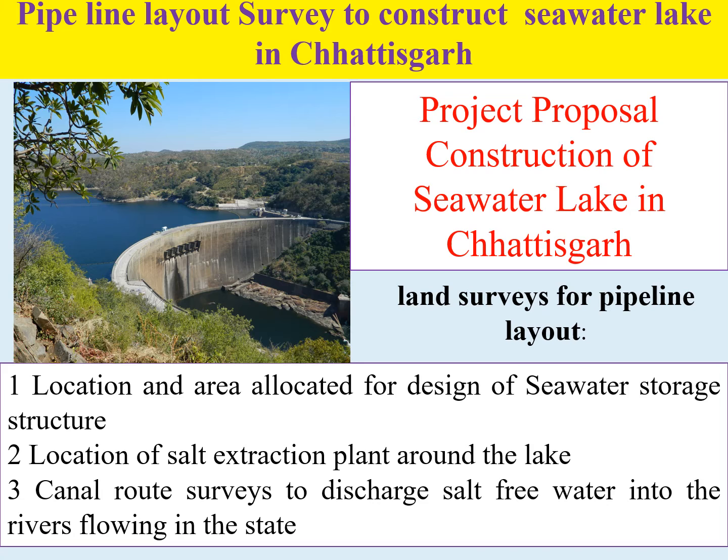Survey methodology. 1. Place traverse stations along the proposed route of pipeline traverse. 2. Establish basic horizontal and vertical controls. 3. Control traverse between traverse stations for horizontal coordinates. 4. Spirit level vertical control, if necessary. Draw paper location for minimum gradient and curvature, and earthwork for suitable cross-section.